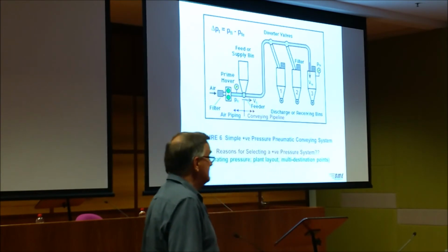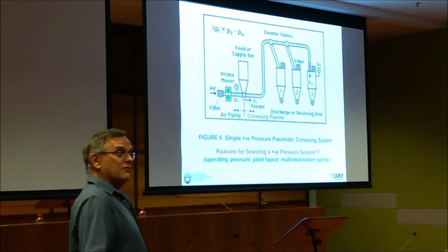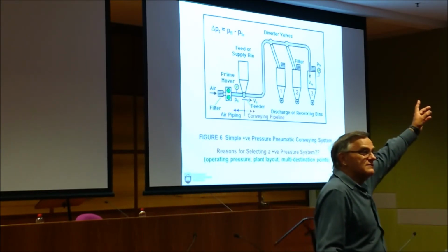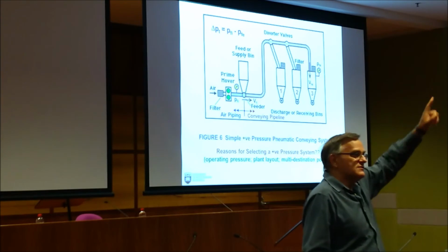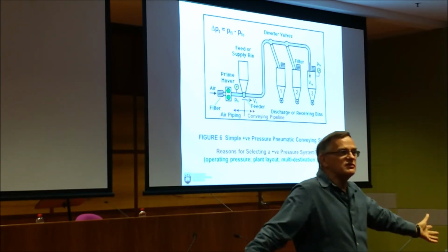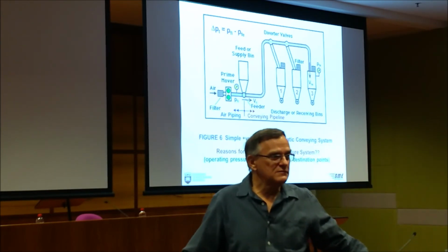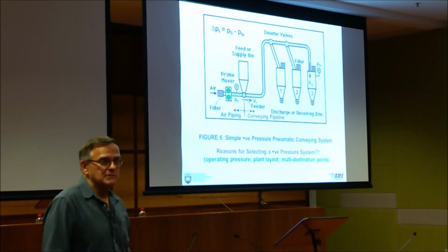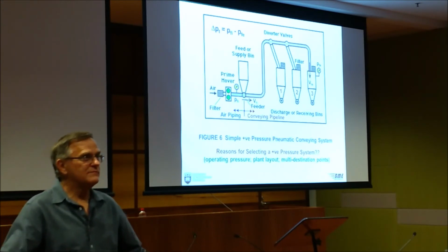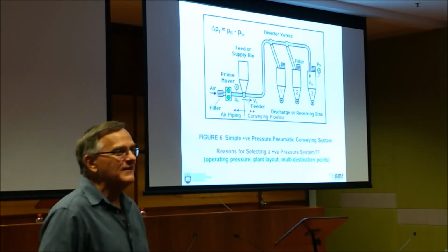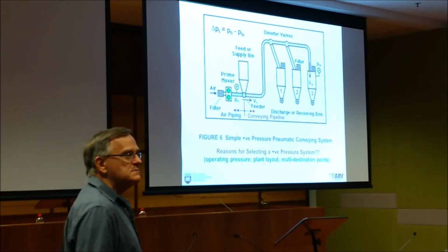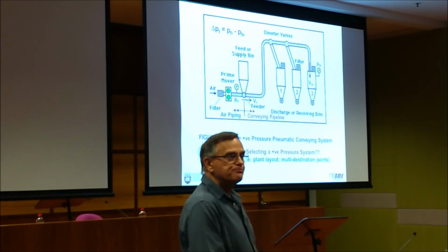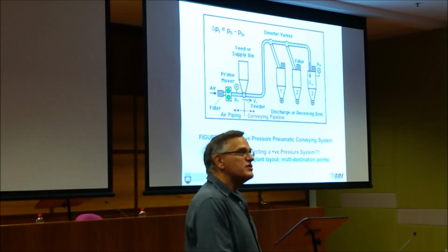Right. So atmospheric pressure on Earth is about what? 100 kilopascals. What's the pressure in space? 0. There's your difference. In vacuum, that's the most you can achieve with any suction device. Do we run up to 100 kPa vacuum? No. Because once you get to 100, nothing's left. So the maximum limit for a vacuum system is generally about 80 kPa between start and finish. Usually we'll limit to 50.